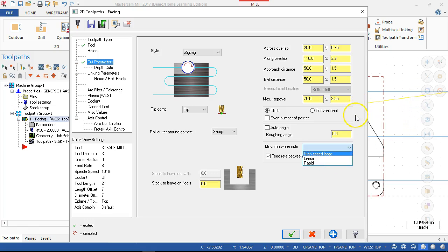I have used rapid and it worked very well, except that when I didn't leave enough lead out, it rapided through about a 1/4 inch of chromoly, 4130 chromoly, and made an interesting sound while it was doing it before the tool broke. All right, so as long as you have enough exit distance and the long overlap to get clear of the part so that it can rapid to that next level, maybe. But really the tool has to be almost 100% engaged for that to be a major concern. But again, it's a concern.